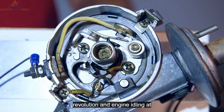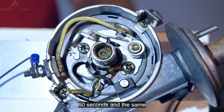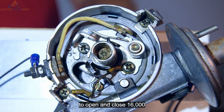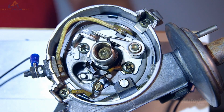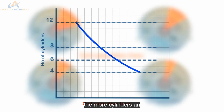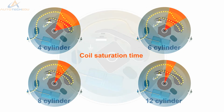An engine idling at 1,000 revolutions per minute has to open and close the contact set 2,000 times in 60 seconds. And the same engine spinning at 8,000 revolutions a minute requires the points to open and close 16,000 times in 60 seconds. This equates to a charge and discharge of about 4 milliseconds. The more cylinders an engine has, the less coil saturation time is available for a given RPM.